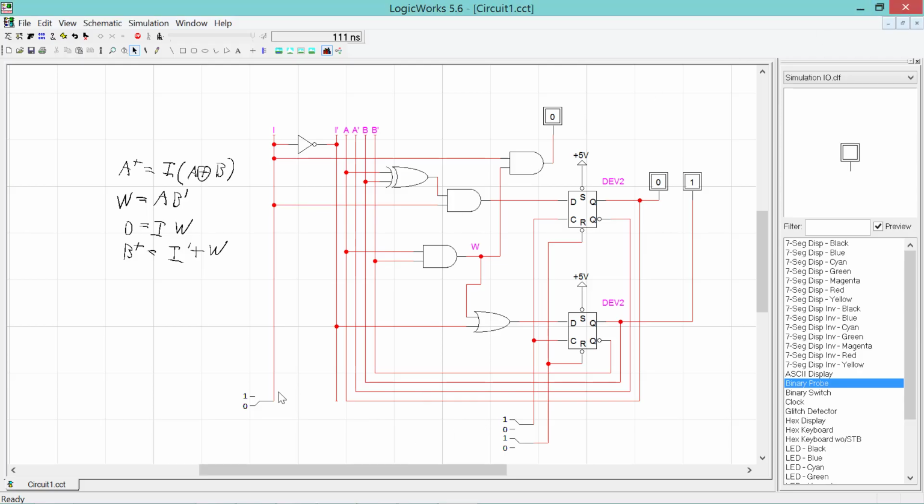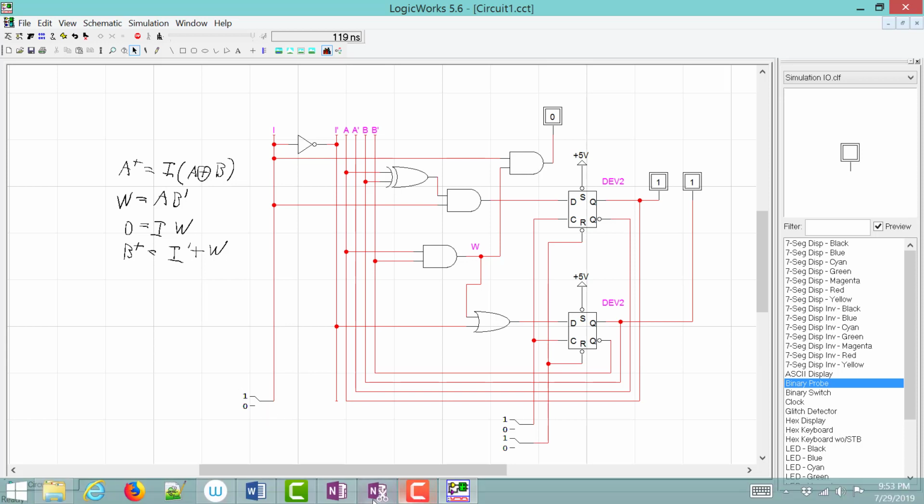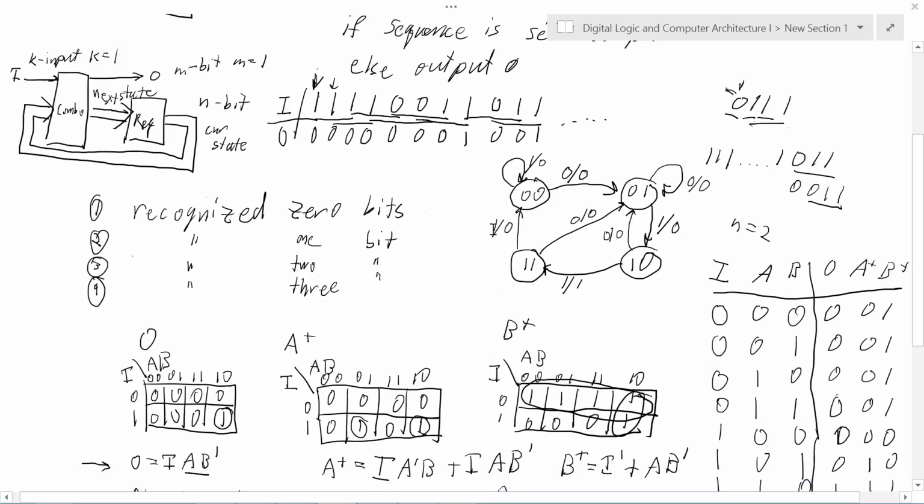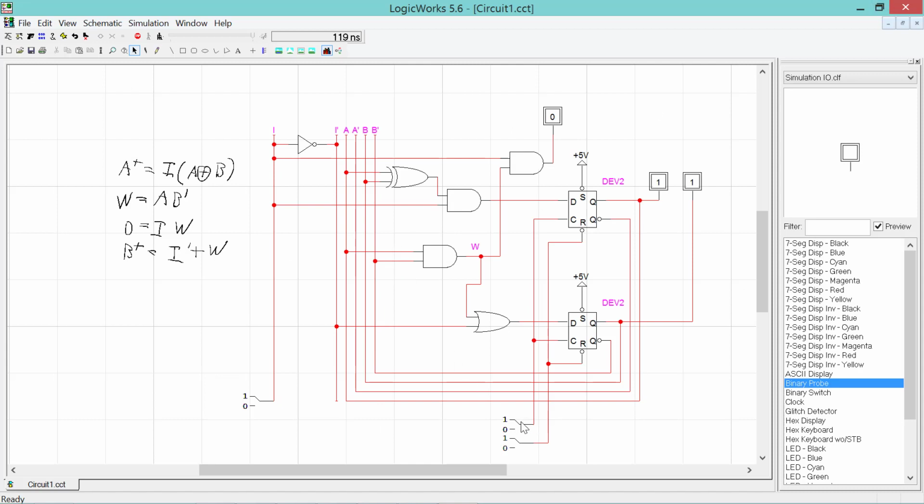Let's try it. Let's bring ourselves to state 3 by clocking a 1. We're in state 2, and then clocking again. We are now in state 3. So if we take an input of 1 here, it should take us to state 0. Input of 1, this state goes from 1, 1 to state 0. And we have confirmed all the edges of our state machine.